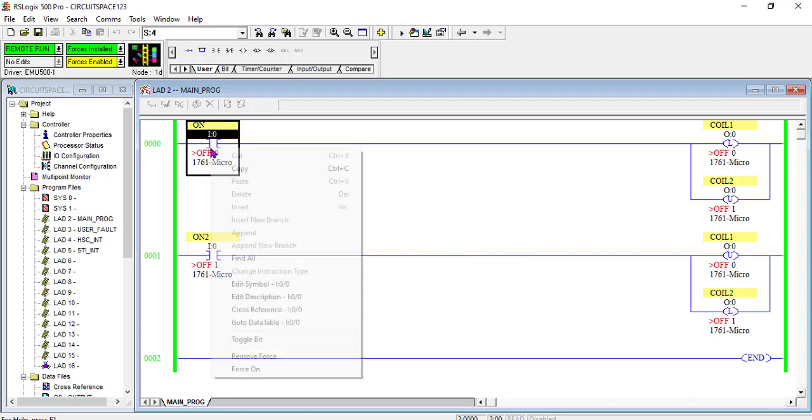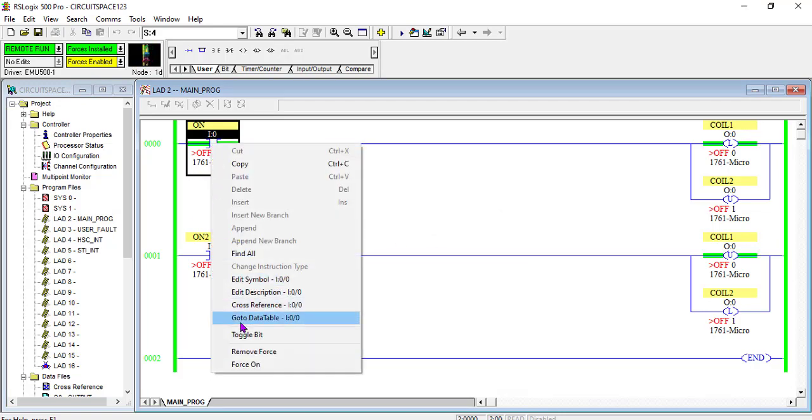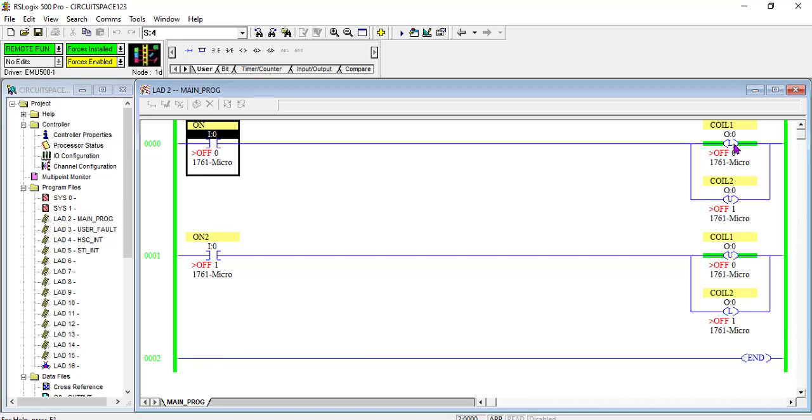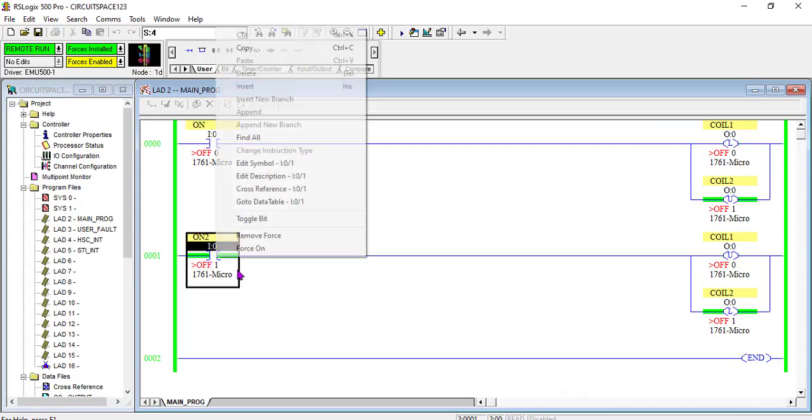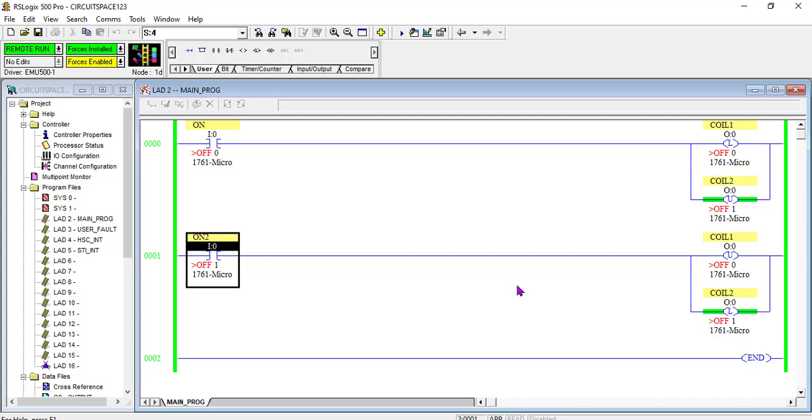Now let me switch on. You can see output 0 is on. Output 1 is not on. This is output 0, beautiful, but output 1 is not on. But if I switch this one on, you see what happened? Output 0 is off and output 1 is on. I'm reversing the situation. So I can use this on 2 contactors to run one motor, forward and reverse.